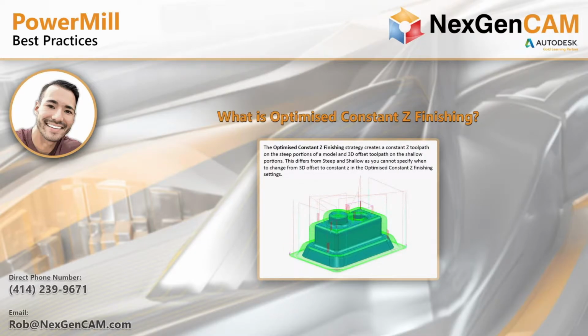Now, what is optimized constant Z finishing? So we already know what constant Z finishing is. There's also an option called optimized constant Z finishing. This is obviously a separate strategy. It creates a constant Z toolpath in the steep portions of a model and a 3D offset only toolpath in the shallow portions, right? So keep that in mind. It's almost identical to the steep and shallow strategy.